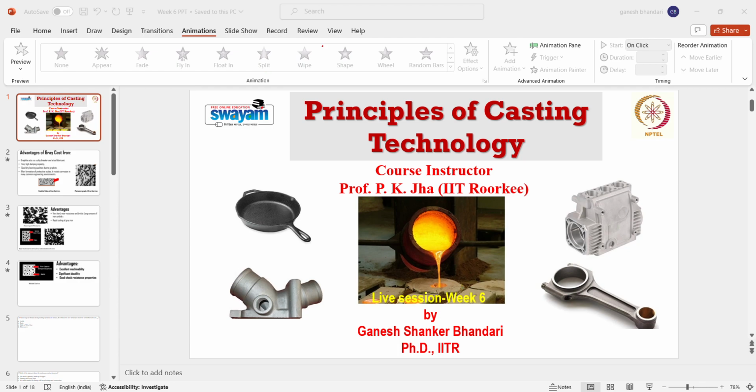According to that process, your metastable phase is going to change into another phase. If we are talking about annealing, the iron carbide phase will get converted from Fe3C into iron and free carbon. So Fe3C is converted into 3 moles of iron plus free carbon. In the process of controlled annealing, the metastable phase of white cast iron decomposes into free carbon and iron, as represented by the reaction.